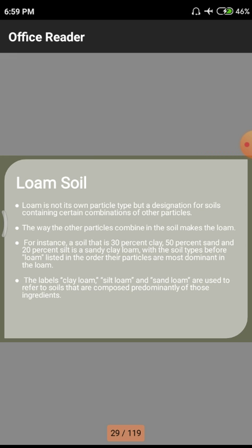Because in some sands we have so many sandy particles that we have less bearing capacity. We all learned about the bearing capacity of soil in RCC. That means we have to go for the design of a particular footing, and this soil bearing capacity will be useful. So total load divided by soil bearing capacity gives the area of the footing, so the soil bearing capacity has a huge role for those different soils.